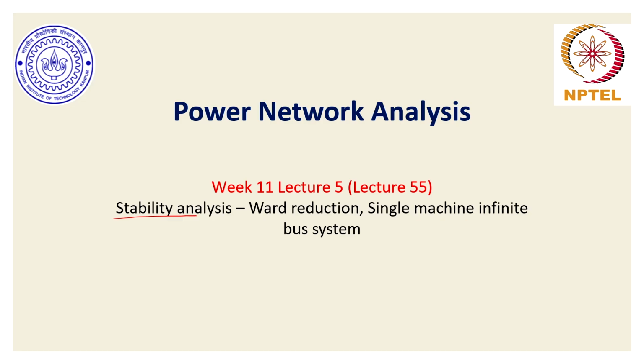So how do we reduce the power networks with different buses into simpler buses so that the corresponding static equations involved in analyzing transient rotor angle stability can be reduced? That technique we will call Ward reduction. And then we will extend this discussion to a SMIB system in full, known as single machine infinite bus system.